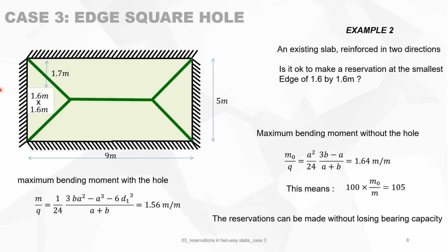But just understand, if you make this hole, all those rebars which are here and in this direction must be anchored sufficiently. Otherwise, it's like the hole is bigger, because when the anchorage is not all okay, the steel cannot yield. So we assume in all our exercises that the anchorage is okay.